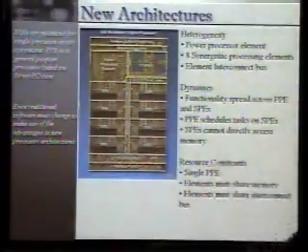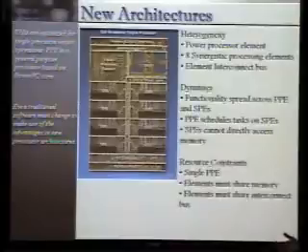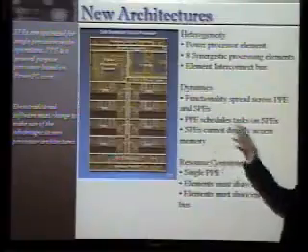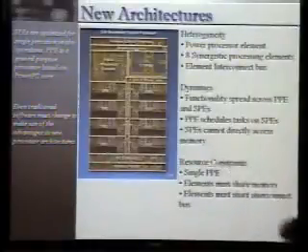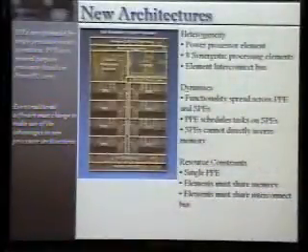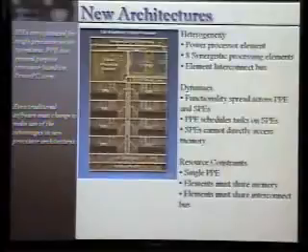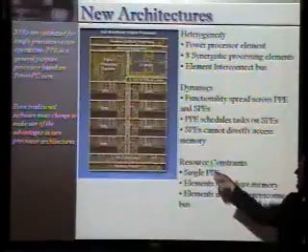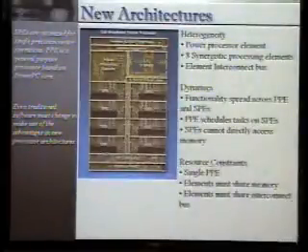So you get some interesting dynamics here. How can these things access memory? How does the PowerPC schedule processes onto these SPEs to use the cell processor efficiently? And of course, there are resource constraints. Not all of these things can talk to memory at the same time. They have to go through this same bus. What's interesting about the cell processor is that it really now puts into the forefront that traditional software design can't escape these sorts of heterogeneous systems. If you want to really get the power out of this thing, you have to figure out how to make software run faster on an architecture like this.